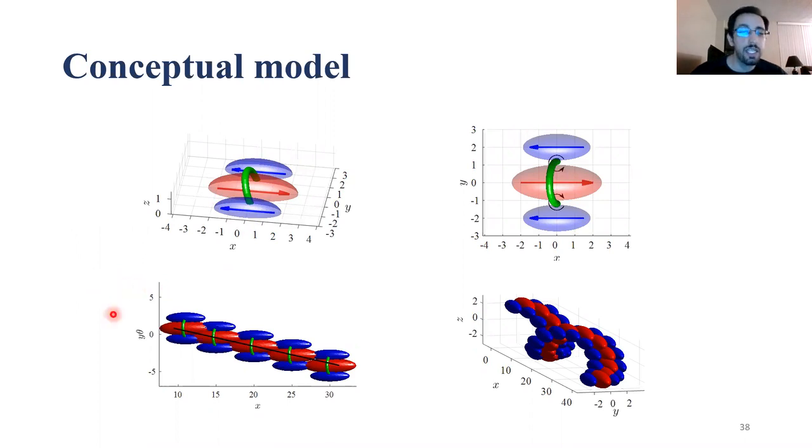And it seems that the eddy structures prefer to form a VLSM that makes an oblique angle with the streamwise direction rather than an axially aligned structure. So this is a two-dimensional view of the VLSM on the streamwise azimuthal plane, and a three-dimensional view of this VLSM becomes this helical structure, which is comprised of a high speed region flanked by two long low speed regions.